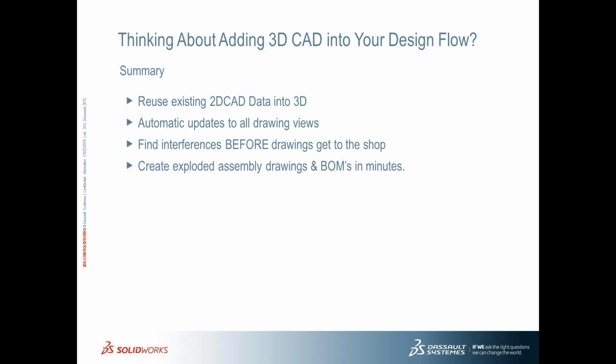So in summary there, again, I was able to very quickly generate the exploded view that you asked for. Outside of that, it was an instant bill of material process. Simply choose the template I want to work with, click the Go button, and we have that bill of materials calculating all the item numbers, part numbers, quantities of each of those items. And then we also use the automatic ballooning just to save us a bit of time.